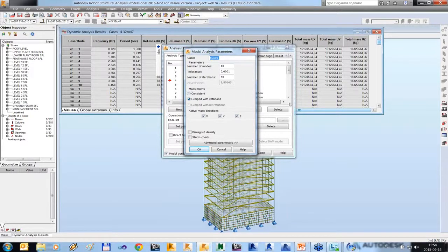The best way, as was mentioned during the presentation, is to compare the calculated masses used in the model. If they are in a reasonable range, we don't have to play with the masses. If not, we can either change the mass matrix type, for example to consistent, or add additional division nodes on some bars near the supports to lose a smaller number of masses by converting them onto nodal supports.